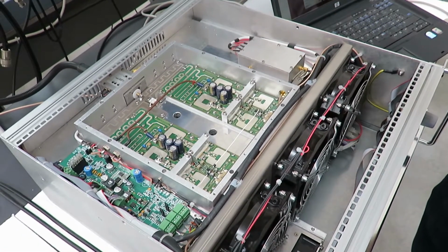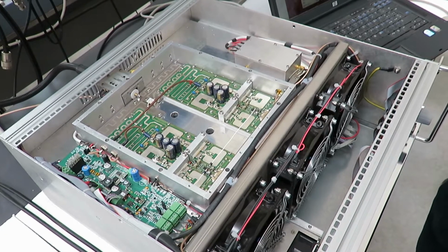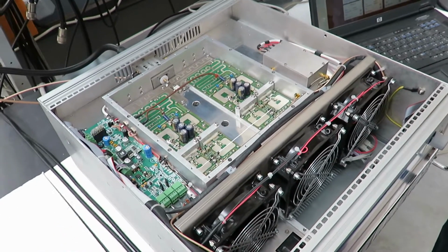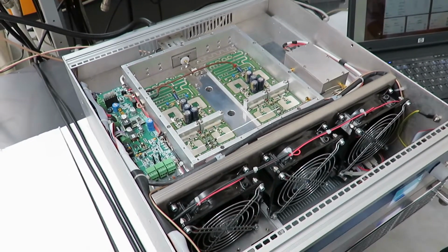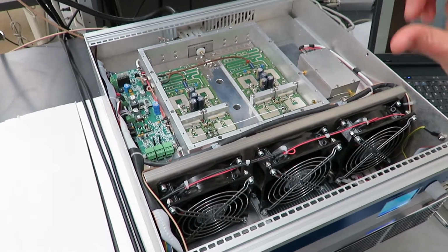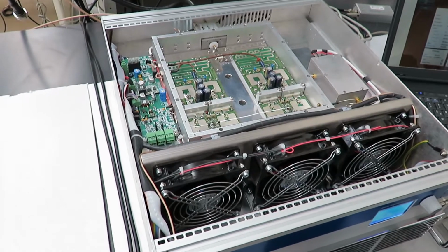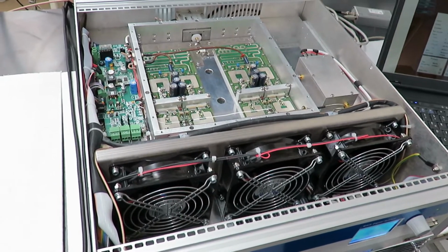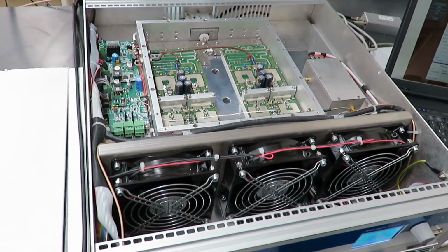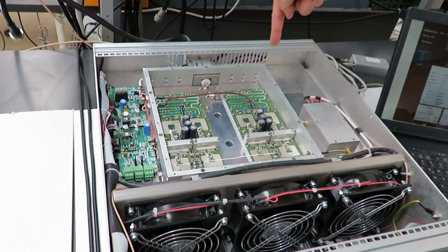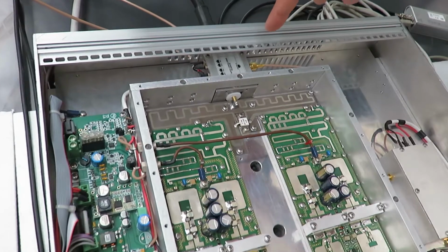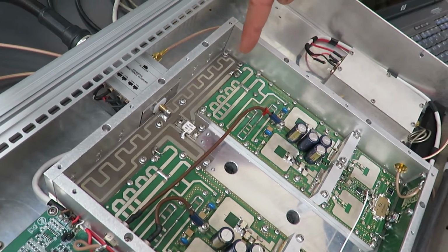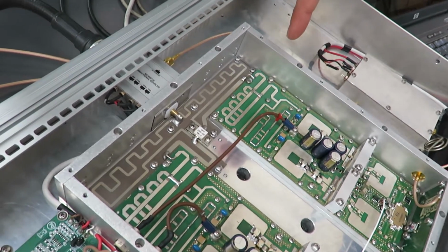This technology is thus very good for digital technology, because all digital broadcasting signals have a very high peak to average ratio. So it makes sense to have an amplifier which is always on, and another amplifier which is on just when needed. That's it. You can see there are two of them working in parallel, and then there is a combiner at the output, just creating the output signal of 500 watt RMS by adding the two contributions. Each of them is 250 watts.